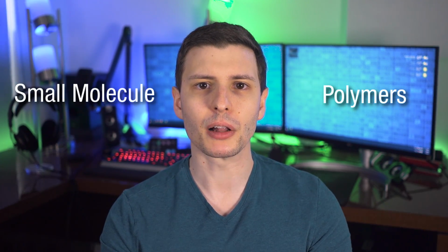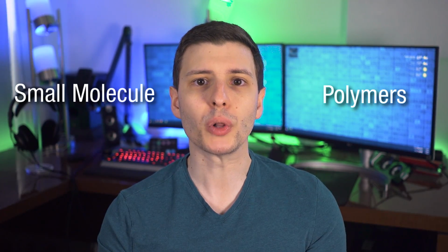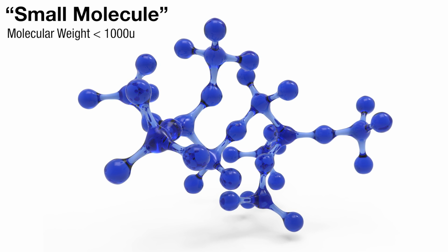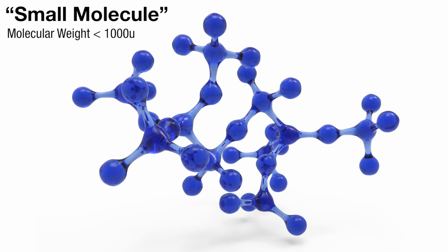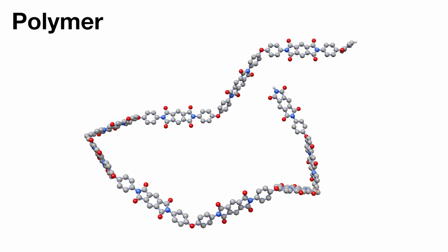Now, you may be wondering more about these organic compounds that are actually used in OLED, and there are several of them used depending on the tech. The current two major types of OLED technology either in use or in development are known as small molecule and polymers. But for some context, at least in 2019, by then, basically all OLEDs were still the small molecule type. In this context, small molecule basically just means a carbon-containing molecule that is literally relatively small, specifically having a molecular weight under about 1,000 or so. On the other hand, polymers are very large molecules formed as long chains, but I'll get to them later.